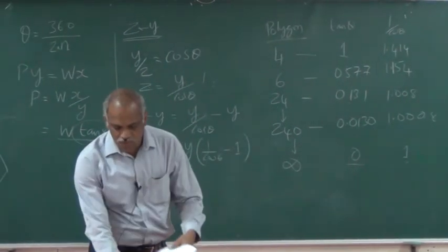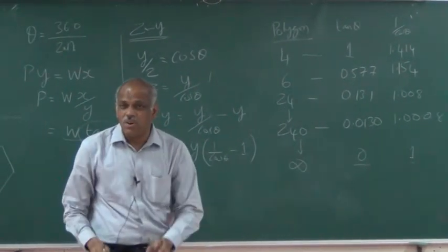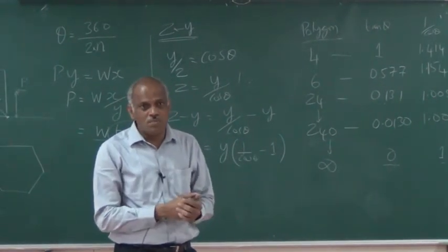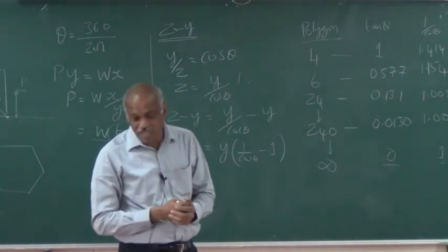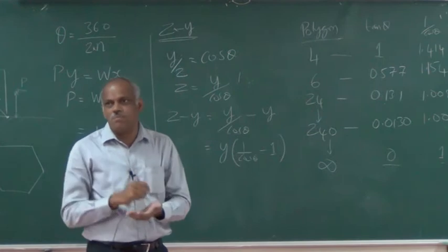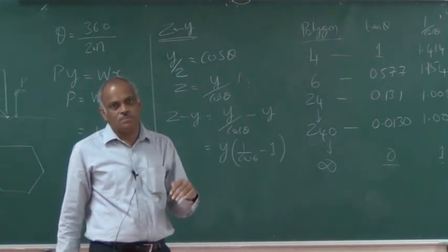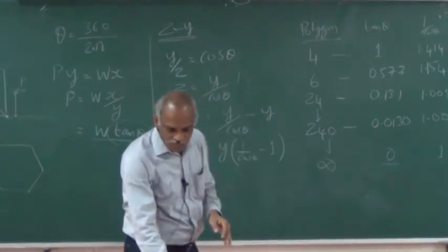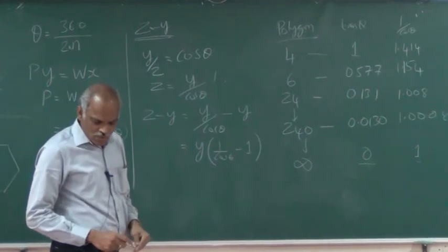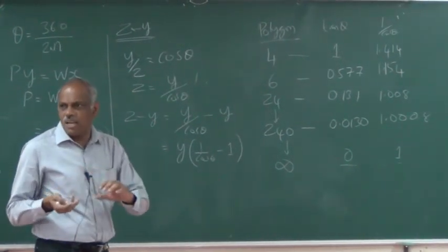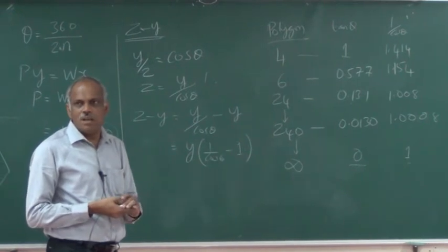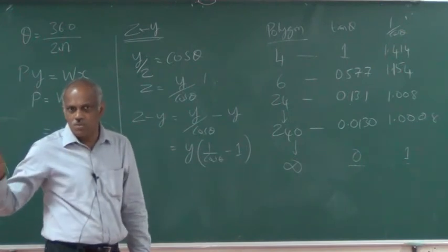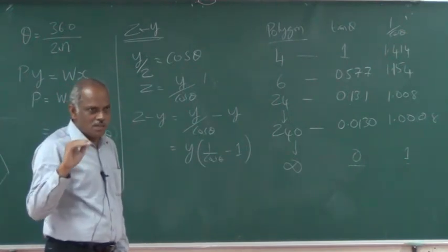But you don't have that. You can have it only if you have a perfect rigid wheel sitting on a perfect rigid surface. That is not possible. Whatever the product, the material that we are dealing with will always have some deformation. Therefore it is not possible to have this option. There will be some deflection at least on the wheel. So we try to make the wheels as hard as possible. That is why train wheels are steel wheels on a steel rail, so that you have a minimum deflection.